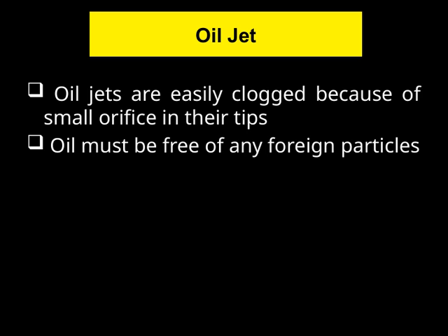If any foreign particles get into the oil, they can easily clog these tiny openings, disrupting the flow. That's why it's absolutely essential that the oil remains free of any foreign particles. Keeping the oil clean ensures that the jets function properly, maintaining optimal engine performance. Remember, the efficiency of the oil jets directly impacts the overall health of the engine, so proper maintenance and cleanliness are key.